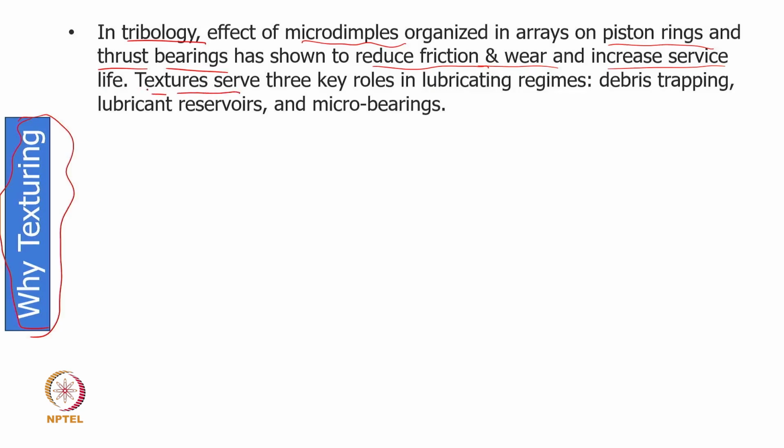We say surface textures serve three key roles, particularly in tribology and in the domain of lubrication. It traps the debris, so it keeps ultra mild wear. It does not increase the wear rate because of the trapping of those particles at the interface between the surfaces.